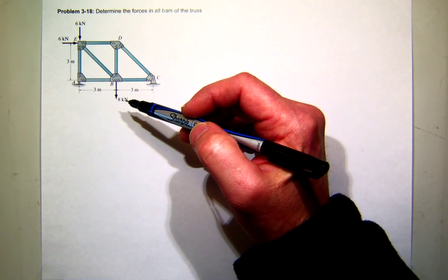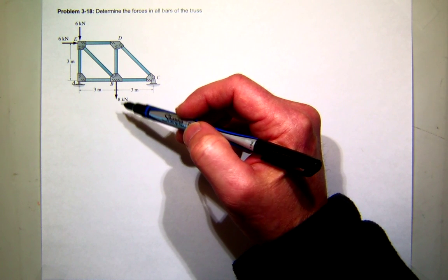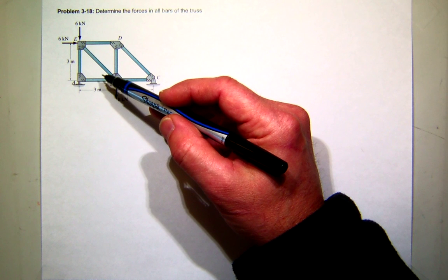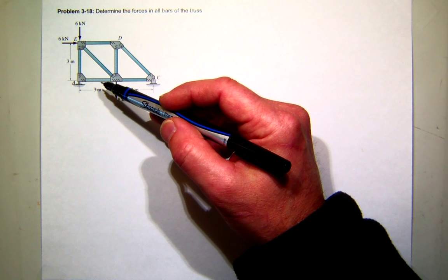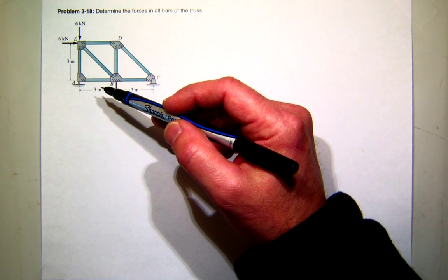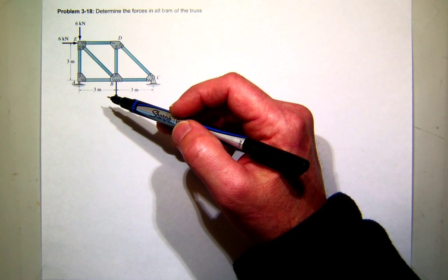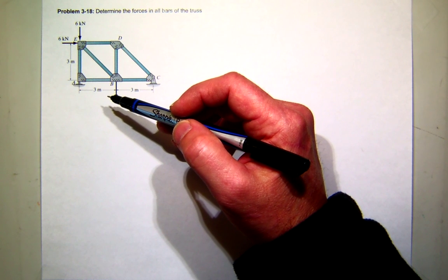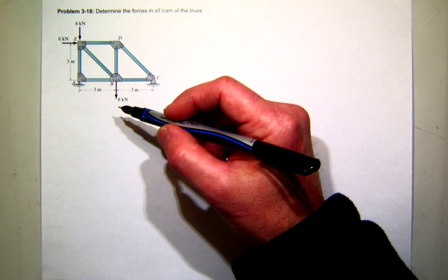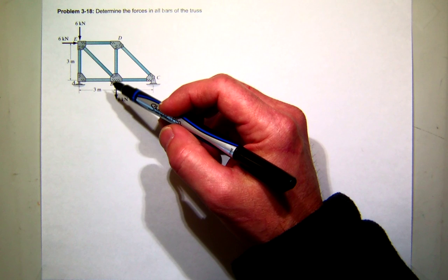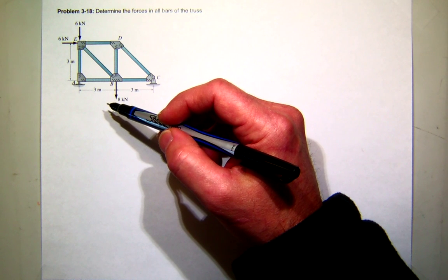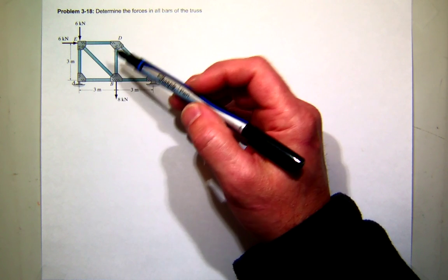Okay, well, with AB, isn't there? I get point A. Now AB, we may find out that AB is 0, but it is not a by inspection 0 force member with the 2 cases that we talked about. I was going to say, if you just look at A, there's no reaction force in the X direction. That seems reasonable.